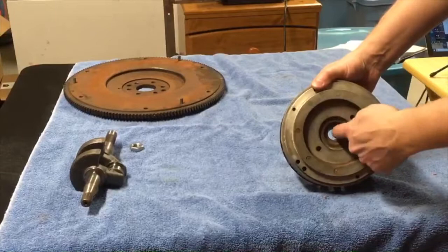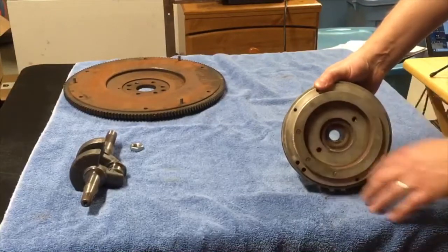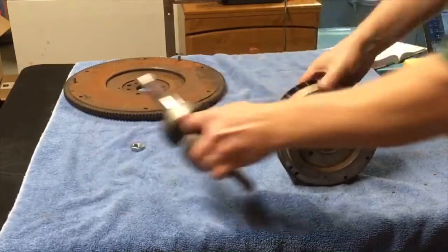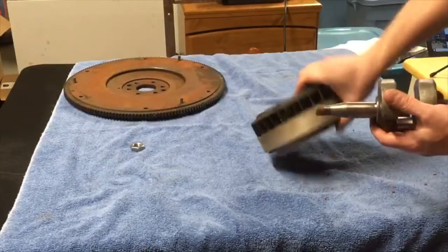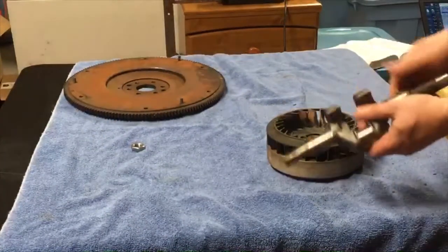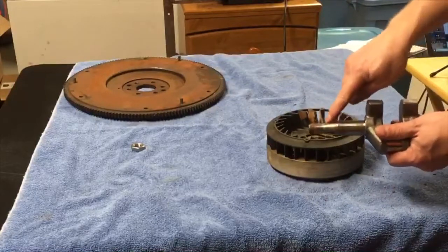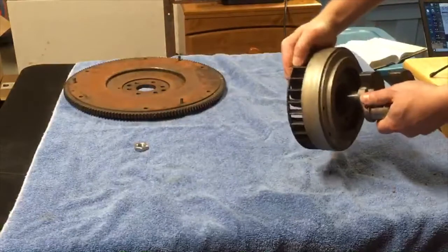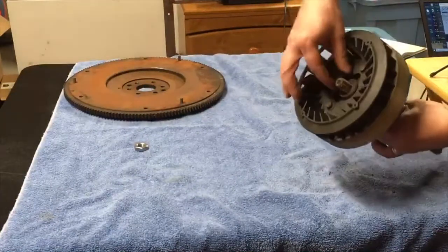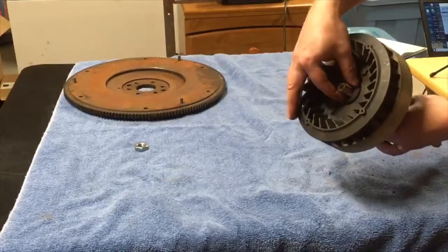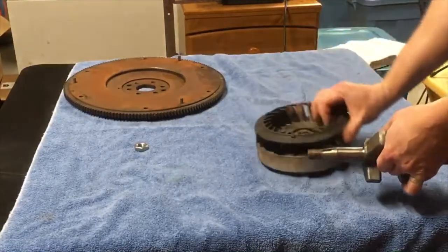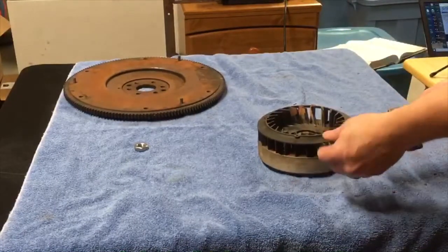There's a taper on the inside of this hub. Probably can't see it, but that taper matches up with the taper in the crank. This just happens to be a crank that goes with this. So there's a taper on the end of the shaft here, and that taper indexes with the taper on the flywheel, and then when the nut goes down to hold it all in place, it locks in place. It's called a wedge mate or a locked or an interference kind of a fit.